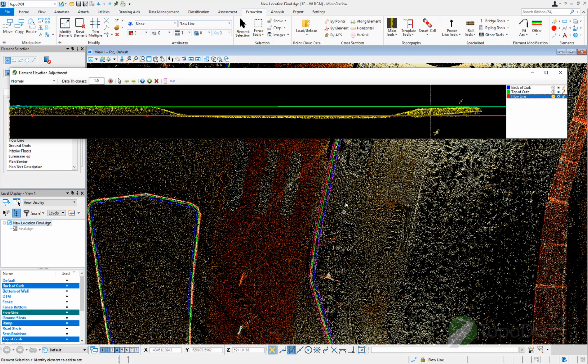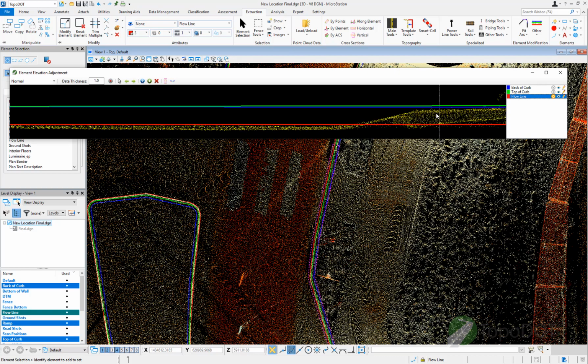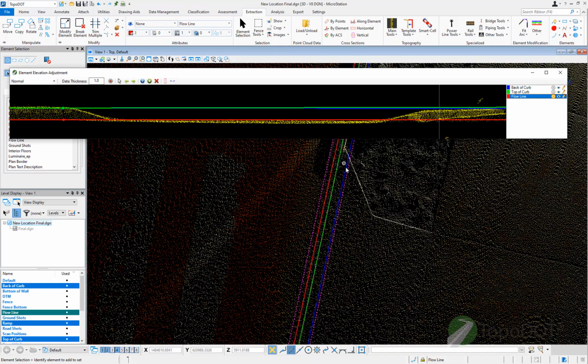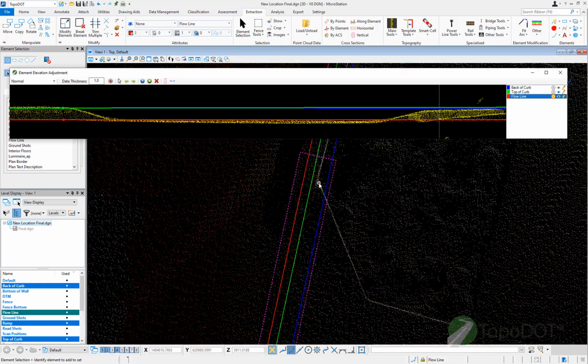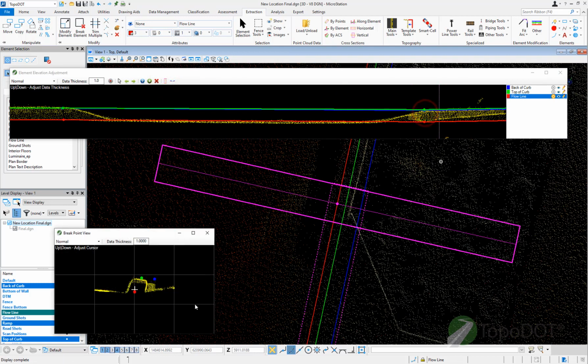So for example here I can see that this placement of the ramp, it's got the first point right here, but maybe not the low points or the next high point. So first I need to ensure that this section of the ramp is actually fitting the top of the curve. So I'm gonna go ahead and click on insert my high points right there and maybe create a cross section through it just to verify it.